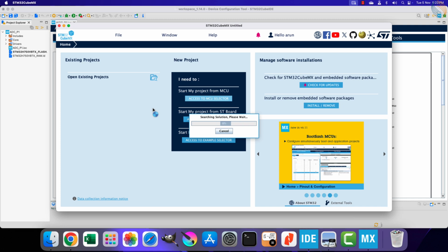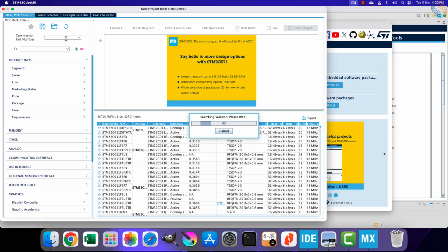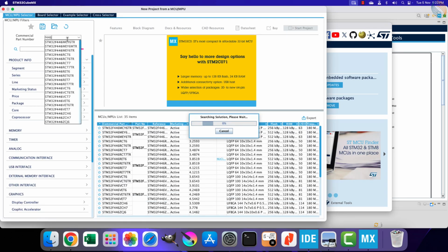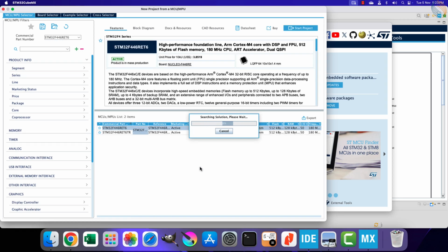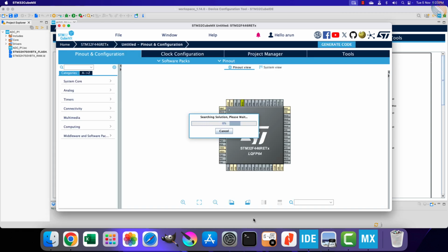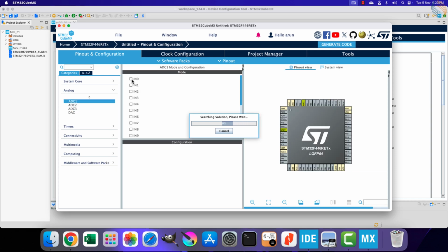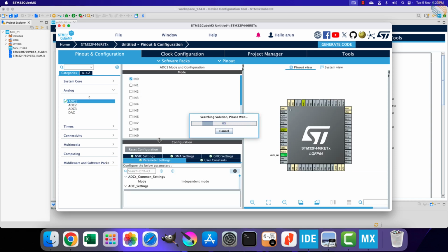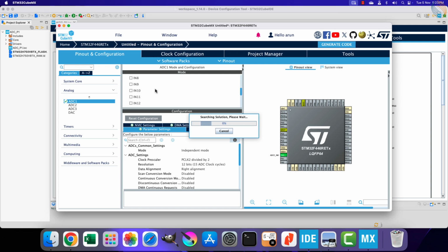Let's see the configuration available on the other STM32 MCUs. Here I am creating a dummy project on CubeMX. We will see the configuration for the F446RE. Let's enable channel 0 of the ADC. Here we do not have the option to choose the differential or single-ended mode. The ADC by default is using the single-ended mode, and we can't use different modes with this MCU. We will see the rest of the configuration in a while.